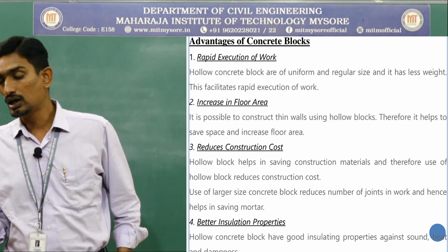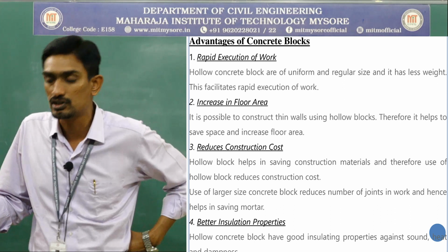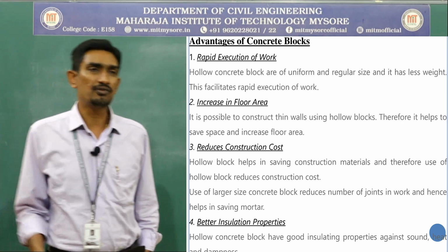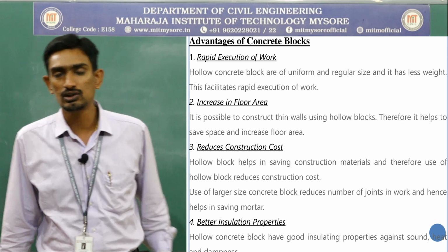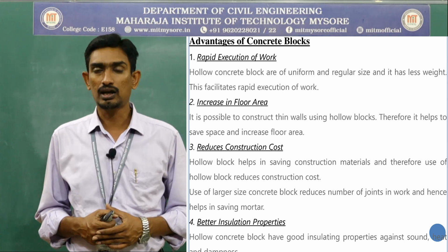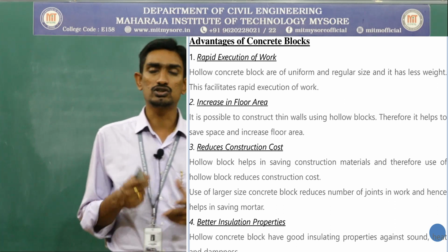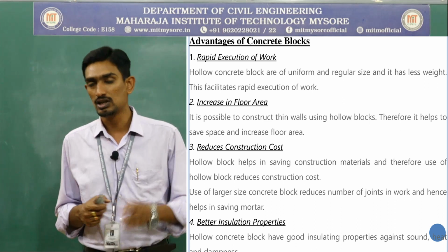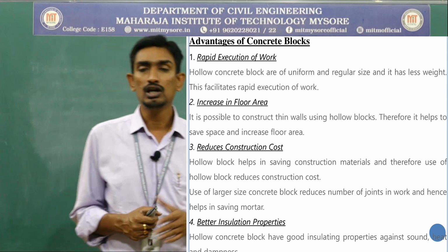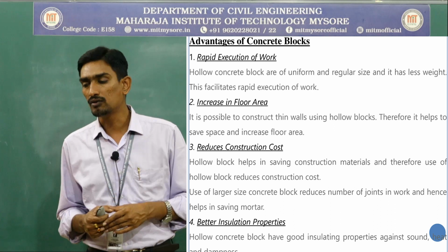Next, reduces construction cost. That means the hollow blocks, you can see that helps in saving construction material, and therefore use of hollow blocks reduces construction cost. Preferably, as I mentioned in yesterday's class, this hollow concrete block is a less load bearing member, or I can say non-load bearing member. Solid concrete block will be called a load bearing unit, hollow concrete block will be called a non-load bearing unit. That means it will bear very little load. Hence this hollow concrete block we can use it.